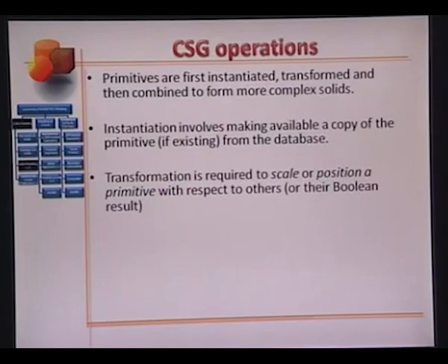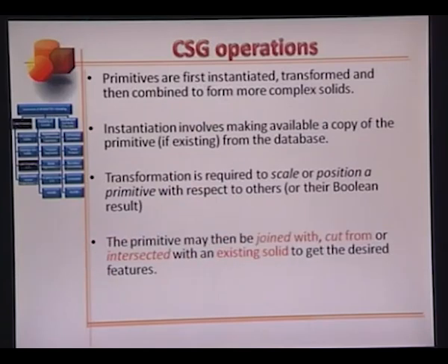Transformation is required to scale or position a primitive with respect to a few others which are available in front of your screen. The primitive may then be joined with, cut from, or intersected with an existing solid to get the desired features. These are the set operations.